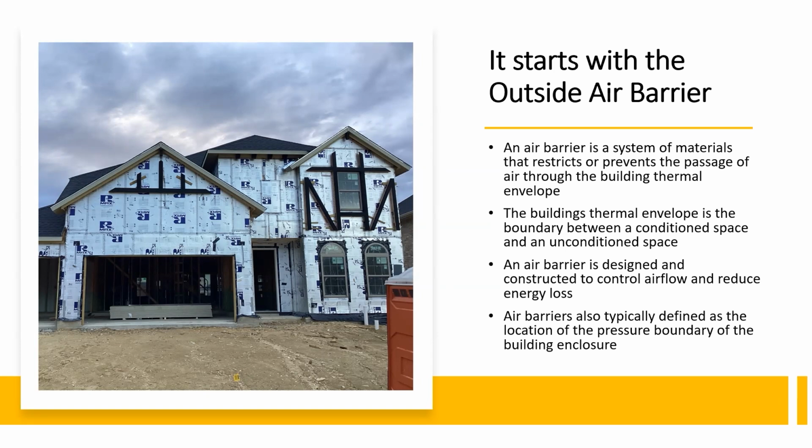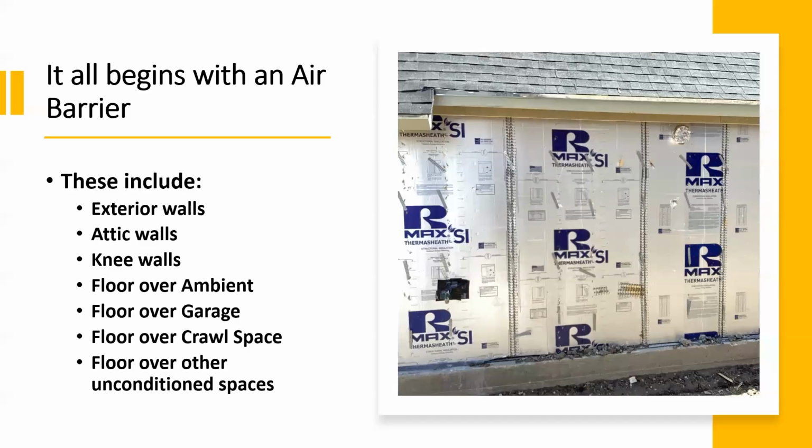So that garage wall, Energy Star talks about that specifically and has specific requirements for the garage wall, that it must be air sealed and separated completely from the rest of the home, not just treated as a separation of garage and home where it just needs to be insulated. No, it needs to be airtight, air sealed completely for contamination.